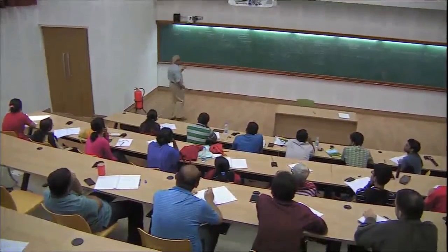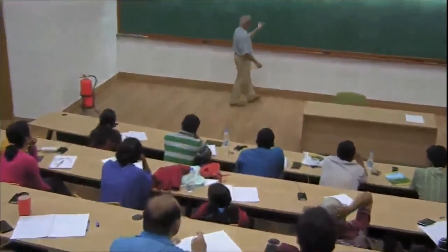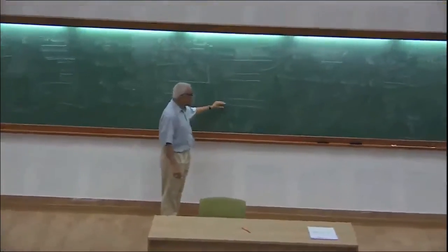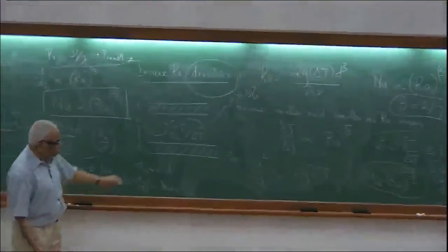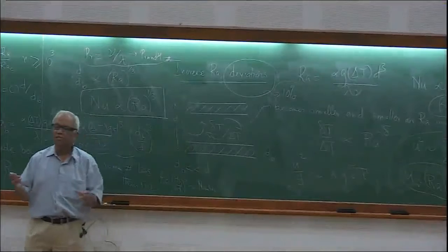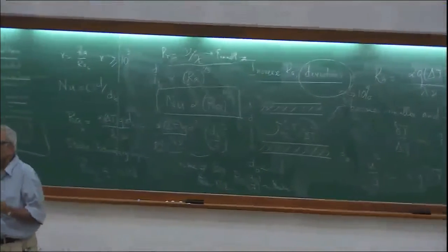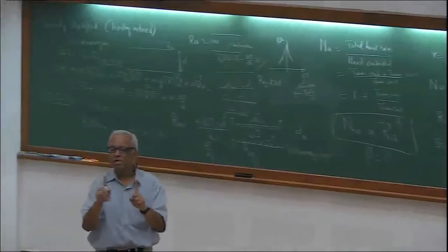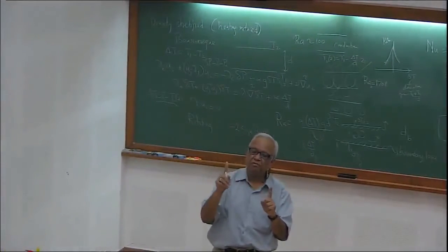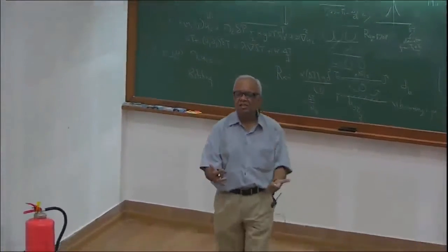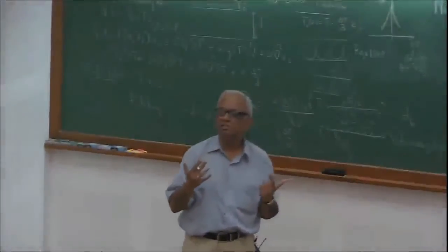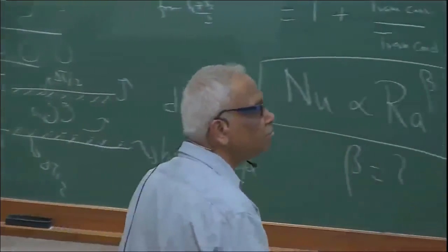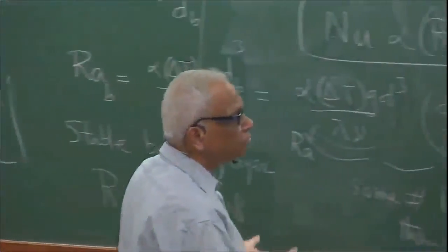But in the argument that you saw over here, the critical Rayleigh number was relevant because it gave the answer by looking at the stability of the boundary layer. That answer is almost there, 1/3, but the experimental difference of 10% from that 1/3 is serious and to be taken seriously. It's a difference which you do see at high Rayleigh numbers, and therefore it has to be addressed.